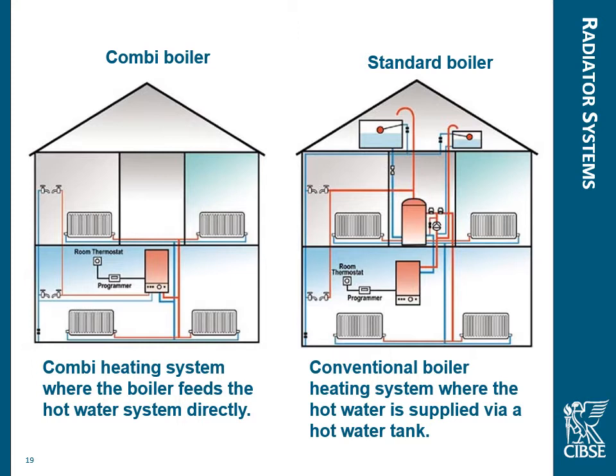Now the combi boiler tends to be favoured by builders and developers and smaller households because it tends to only do one thing at the same time. Also, when you look at the pipe work and what's involved in the installation of it, there's a lot less involved there. There's no tanks and pumps and header tanks in the loft, etc. The disadvantage of that is it doesn't have any sort of backups. If the boiler stops, everything stops, and if the water supply stops, again everything stops.